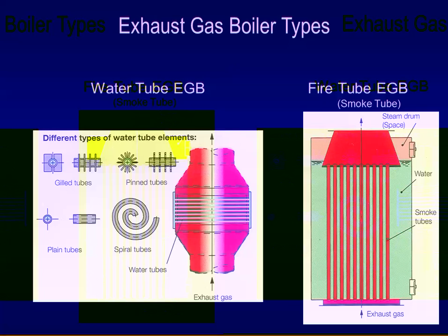You typically get exhaust gas boiler fires during maneuvering, but it can happen at any time when the engine is running. You will know if you get an exhaust gas boiler fire. Typically, one of the things the mates will start reporting to you is that there's a lot of sparks coming out the stack. The turbos may start to surge. Your exhaust temps are going to go up, and there's usually a pyrometer in the stack that will indicate to you that there is a problem.